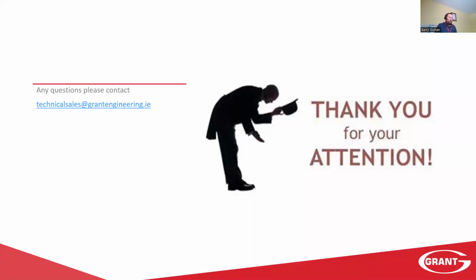For anyone that is interested in heat loss calculations or what goes into it, I would recommend the CIBSE Heating Design Guide. It gives step-by-step how to do a heat loss calculation, what's involved, what your figures are from design temperatures, from air changes, etc. And also SR50-1 and SR50-4. That will provide every bit of information needed in order to ensure that heat loss calculations are completed